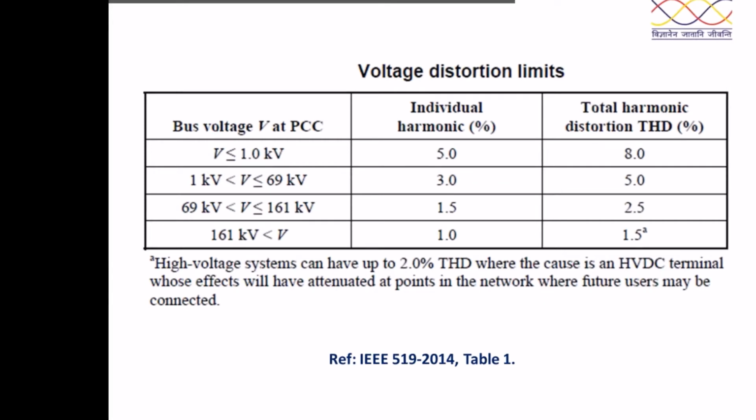Whenever you measure harmonic distortion, most measuring instruments give the current distortion with respect to the fundamental current measured at that instant. Therefore, that is what we call THDI. But when you measure that current with respect to the maximum load current, then the distortion may be lower.